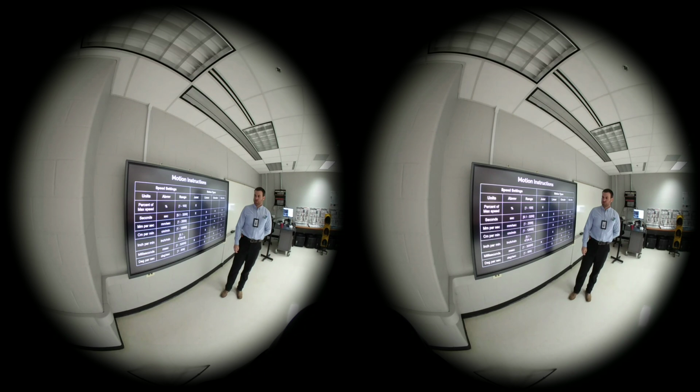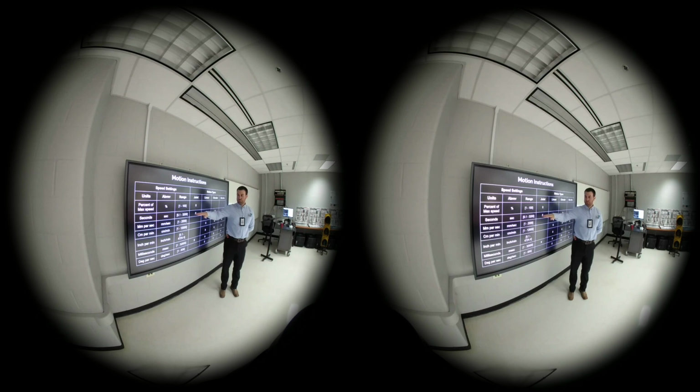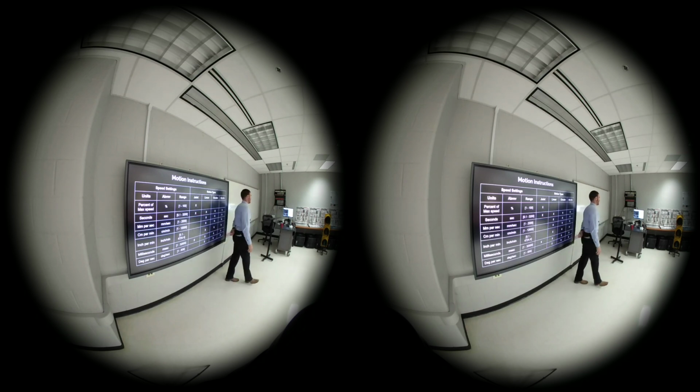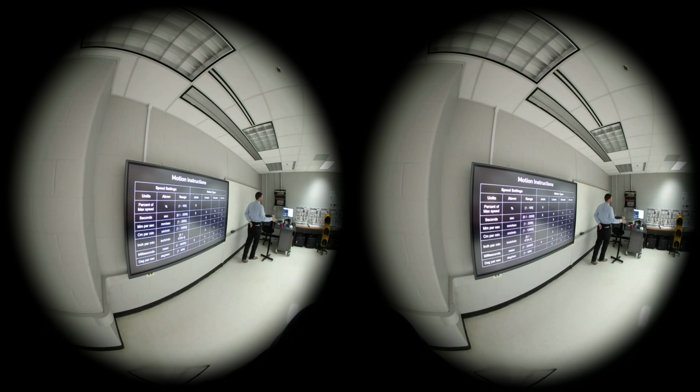When you're talking about cycle times, I tell a lot of my students to program in seconds, because you don't necessarily need to have the most rapid accelerations. Just because you can do 4,724 inches per minute doesn't mean you should, because force equals mass times acceleration, right? Newtonian physics. When you do that, you induce a lot of force on your part or on your payload. So a lot of times we resort to just doing seconds, because that's what your cycle time and performance metrics are based on anyway.